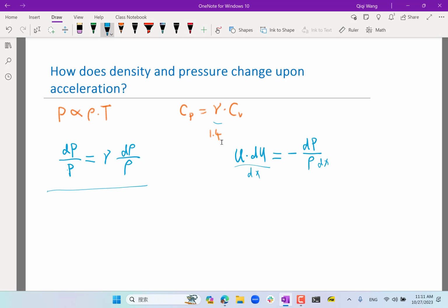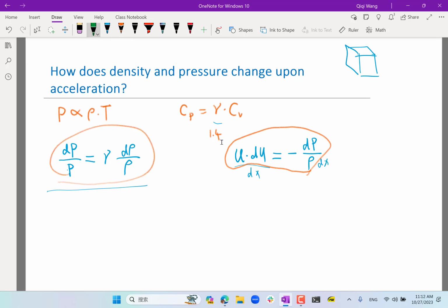So yeah, I think we derived it by basically taking a volume and saying pressure times the area is equal to force, and therefore delta pressure divided by dx gets into the force per unit volume, and then divide by another rho. So the division by rho changes the force per volume into force per mass, right? And that is acceleration. So this is the equation. This is the second equation we used. So this equation, without the dx, we combined with this equation to derive something quite remarkable.